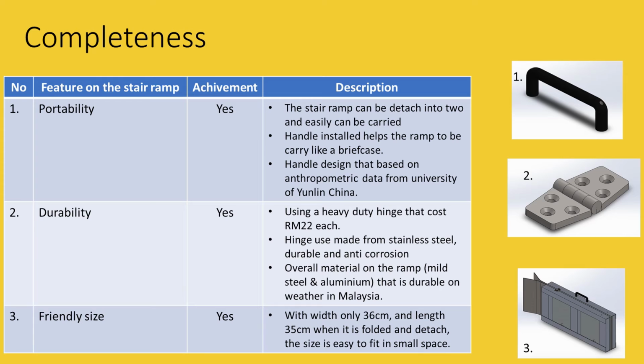Secondly is durability. We use a heavy-duty hinge that costs 22 ringgit each. The hinge is made from stainless steel, durable and anti-corrosion. The overall material of the ramp is mild steel and aluminium, which is durable against the weather in Malaysia.